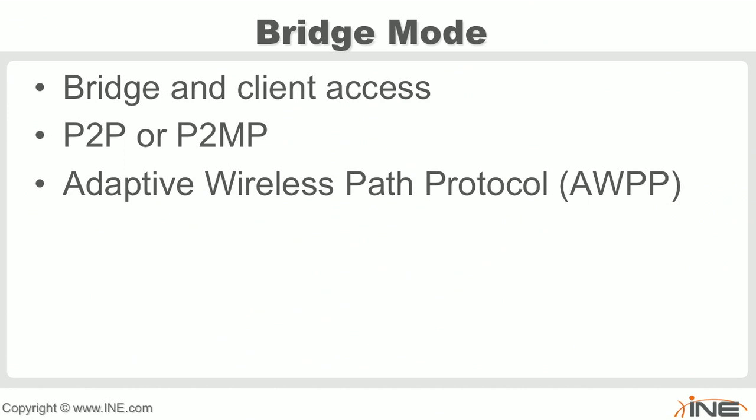A lot of times it actually is easier to get Ethernet out to an area than it is to get AC power, especially because we can do power over Ethernet. And, at least according to most US building code, we don't have to put Ethernet in a metal tube type of channel in order to run it, whereas we do with AC power. But for whatever reason, there are certainly environments where we can get AC power to an access point.